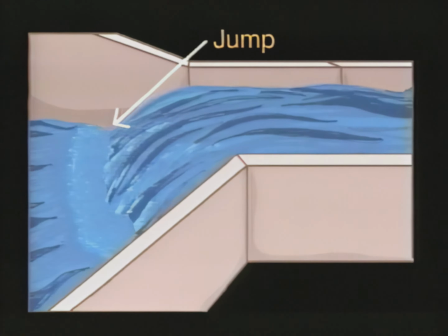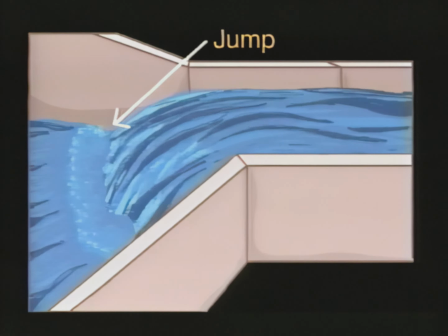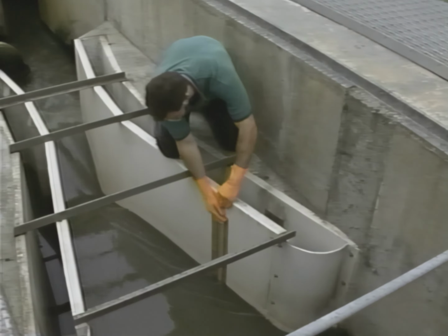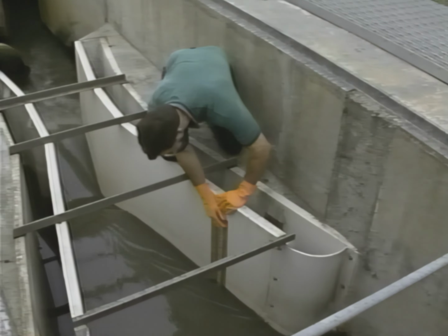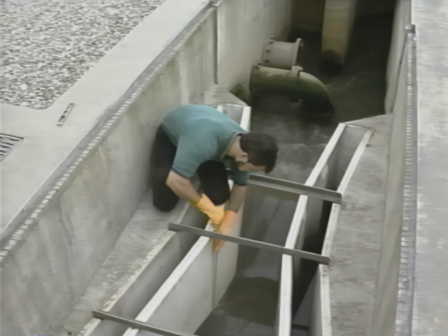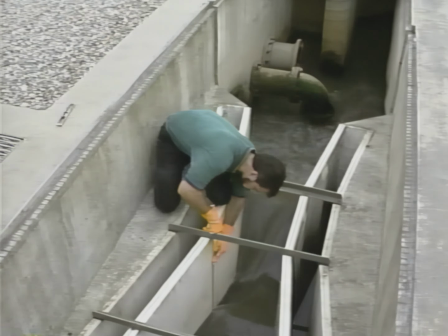If you aren't sure whether the flow is free or submerged, a simple calculation will answer the question. First, take a liquid head measurement in the convergence section, as I mentioned before. At the same time, take an additional head measurement at the point in the throat just before the flow enters the divergence section. Most treatment plants don't have measurement devices here, so just use the yardstick.